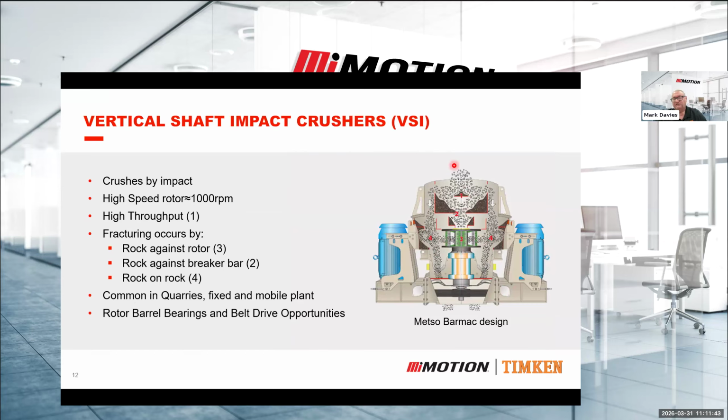And the way that works is two thirds of the ore flows through the center of the crusher, and then a certain amount flows around the outside, which then causes the ore in the center to hit the impeller. It gets flung out with centrifugal force at high speed, and that impacts the rock going around the outside of the crusher, and it's basically a rock on rock action. So it's using the speed of the rock and the inertia of those rock particles to actually break the rock up, and it does produce a very consistent rock output.